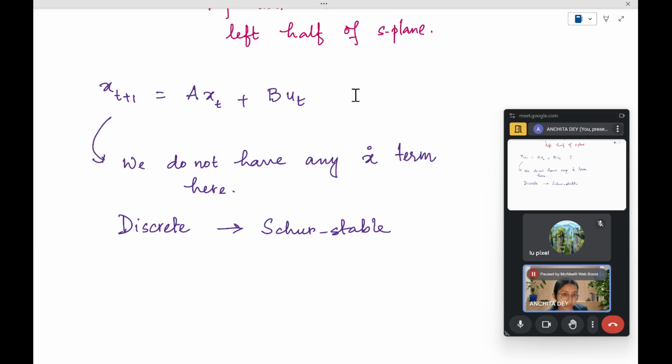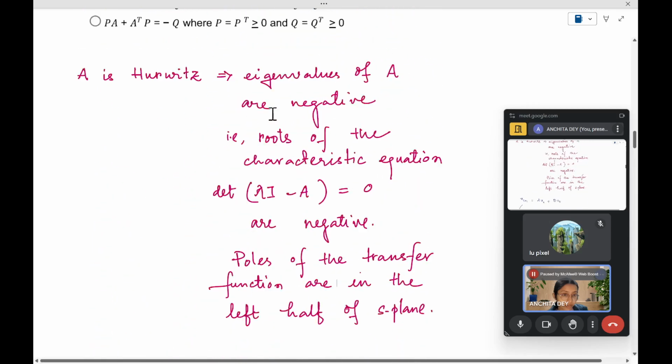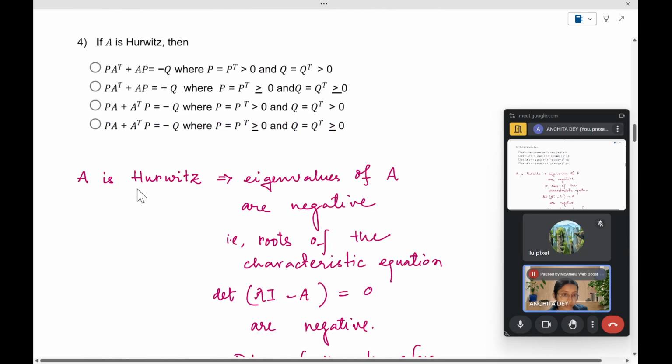In the Z domain, all the poles lying inside the unit circle lead to a stable system. That means now you would want the modulus of your eigenvalues to be less than 1, between -1 and 1, which is the unit circle. Anyway, that was a side tip just for this question.